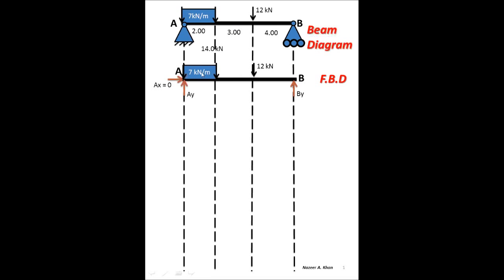I have all of my magnitudes that I need. If you notice for AX, which is this reactant force right there, I already have a magnitude of 0. The reason for this is that we don't have any horizontal component to cause a reaction from this particular support. Okay, if we had an angular force, then the component would cause a reaction. We would have a magnitude other than 0 for this. Okay, the next thing to do is to go and calculate the magnitude of AY and BY.